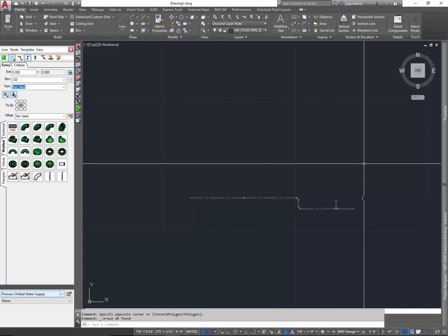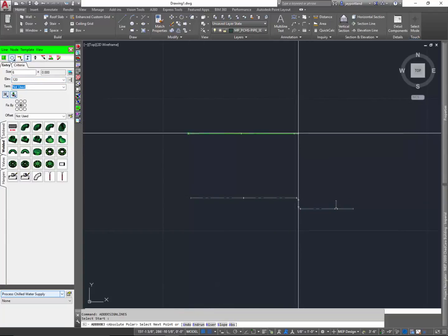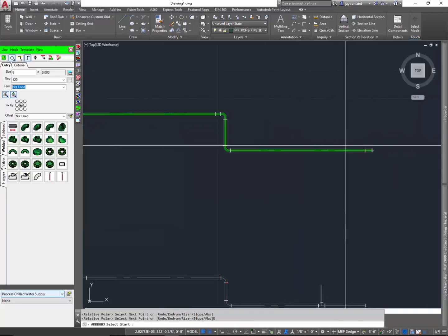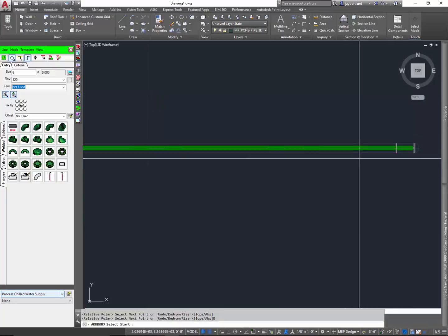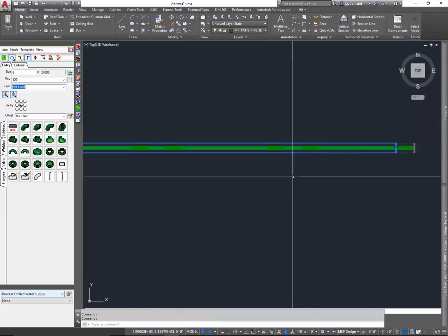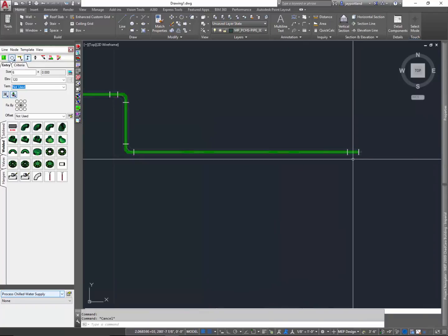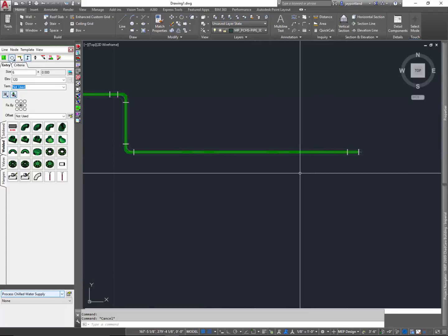Now, a few additional details. We are going to add in some 6-inch piping at 120 inches. Let's go ahead and add some piping now. So that was the design line, and what the design line does is it facilitates adding these components. Now, you'll notice that I have a big, heavy center line here that represents my design line, okay? But then I also have the piping that's associated right around it here, and according to my minimum cut lengths of 20 feet, which is 240 inches, that's where the shop weld will be placed, okay?